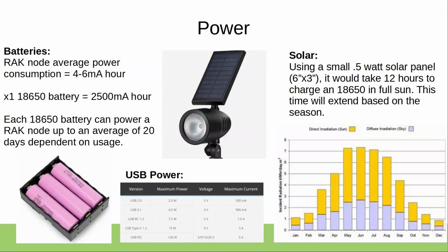Quick note on these as well is watch the polarity. Yes. Because with connectors, there's not necessarily a standard polarity, and they're all marked on the boards, but just make sure you're matching the right polarity. I've definitely never cooked one messing that up before. Yeah, they are a little sensitive. I mean, you're dealing with bare board electronics. Discretion is good, you know, ground yourself, make sure you're double checking your soldering, especially with the T-Beams for their screens. They typically come and you have to solder the screens on, which is just like 5 header pins, but I've still managed to kill one doing that.